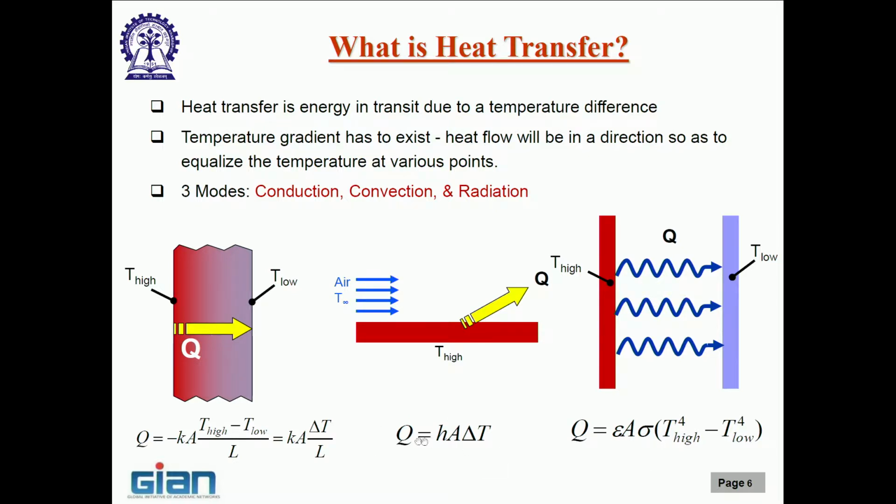The next mode is convection. Now, convection is what we call in the thermofluids language conduction which is aided by advection or bulk flow of the fluid. But essentially, for practical purposes, what it means is it is not just transfer of energy due to vibration of molecules, atoms and electrons and phonons, but it is also due to bulk movement of the fluid. So, you need to have a fluid that can flow.